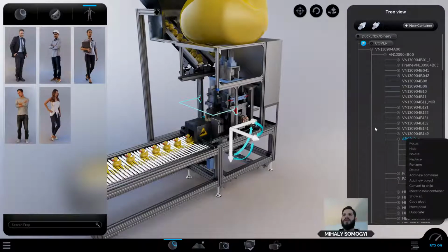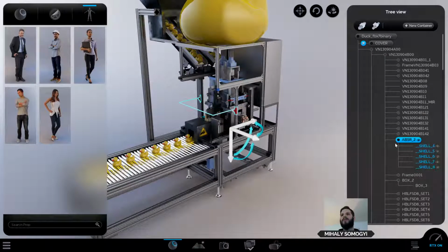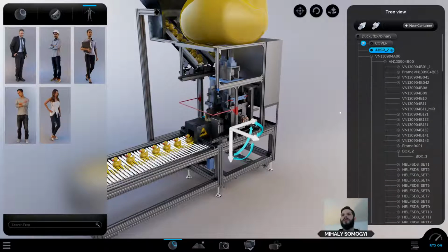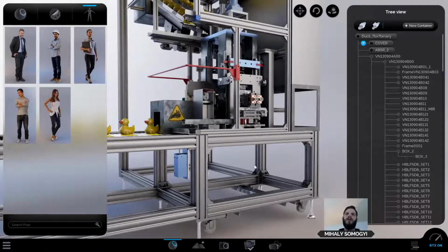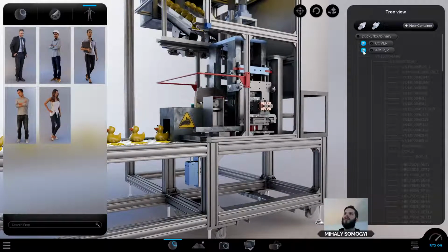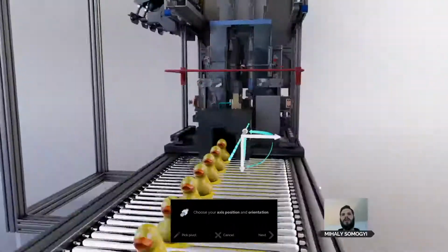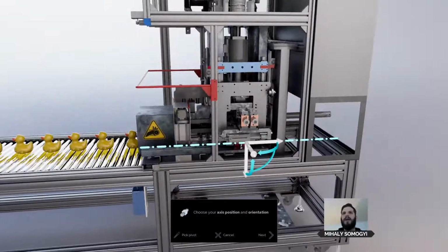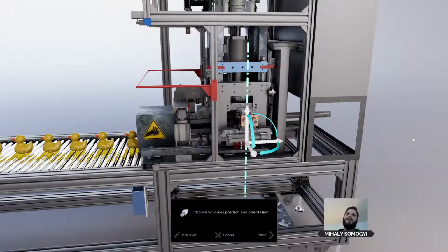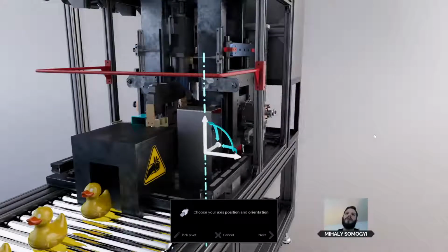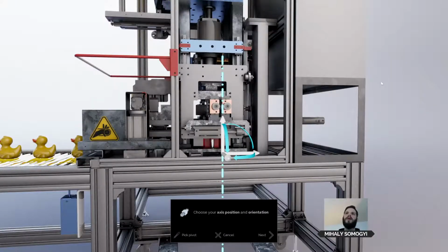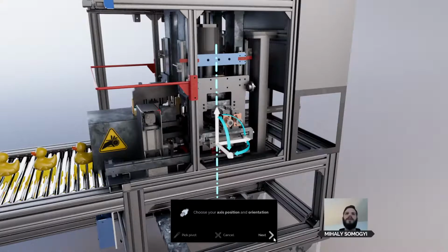And I'm just going to do a simple right click and use convert to child. And once again, drag it all the way up so it's easier to find. Once this is done, I'm just going to put a simple sliding constraint on it, so drag and drop on the blue dot again. And now you can see that my axes are 90 degrees off, because I would like this piece to slide up and down. So I'm just going to use my previous trick, but this time to define the axis. Hold down Shift and do a 90-degree rotation. Very easy. And since here I only care about the direction of the movement, I don't even have anything else to do. So I'm just going to click Next,